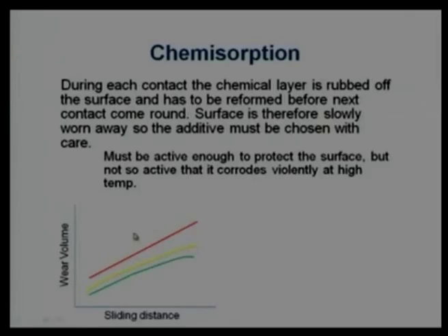And this shows up with the physical absorption. In the physical absorption case, most of the time the wear of the lubricant layer is happening, detachment of the lubricant layer is happening. It is not reacting with the substance, not reacting with the component, not reacting with the material. Naturally, wear rate in the case of physical absorption will be lower than chemisorption, whatever the situation.